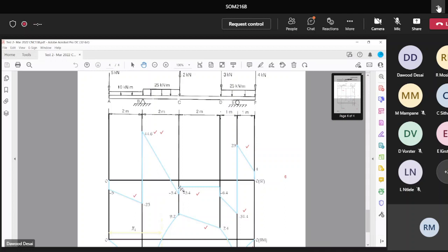Now you can plot these points directly from the neutral axis. It's not a continuation like the shear force. Okay, so here we are now. Just make it a bit big so I don't confuse things. Right, so there are the values now. From here, you draw down -30. The next one, you put that force, 9.2. Then you put that one there, that's what you calculated. All the calculated values, you just put dots from the 0 according to scale.